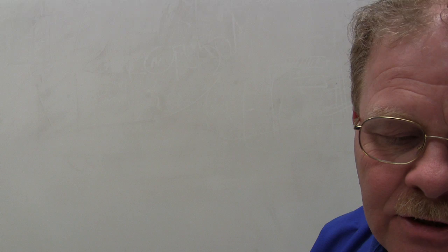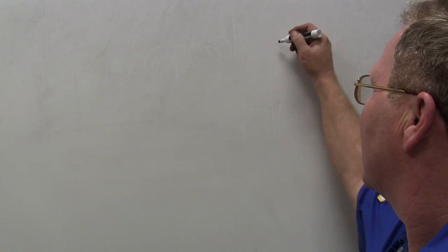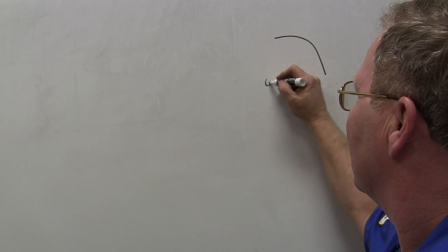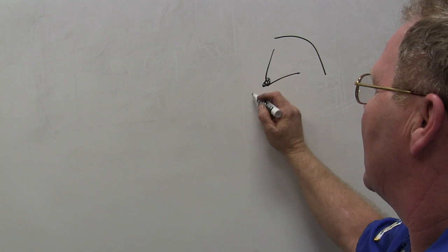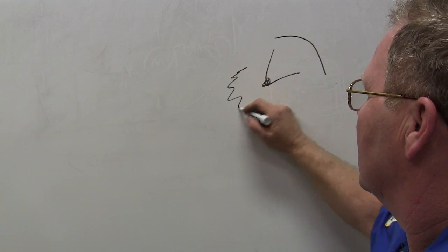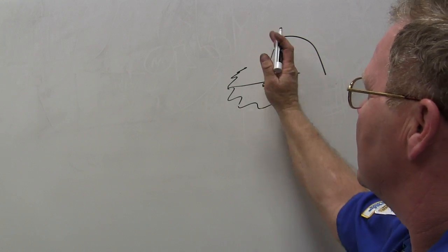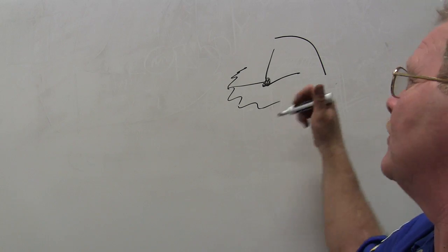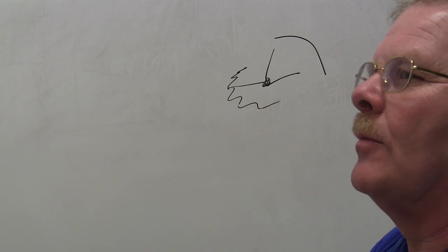Which sensor has a switch that controls the electric fuel pump? That would be the vane airflow sensor, which has a peculiar shaped box, and it's got an L-shaped flapper in it. On the top side of this L-shaped flapper, up in the electronic part, there's a little thing, and whenever the flapper moves, it slides. As soon as it starts to move, when you're spinning the engine over, it's going to close a little set of contacts that's going to operate your fuel pump.